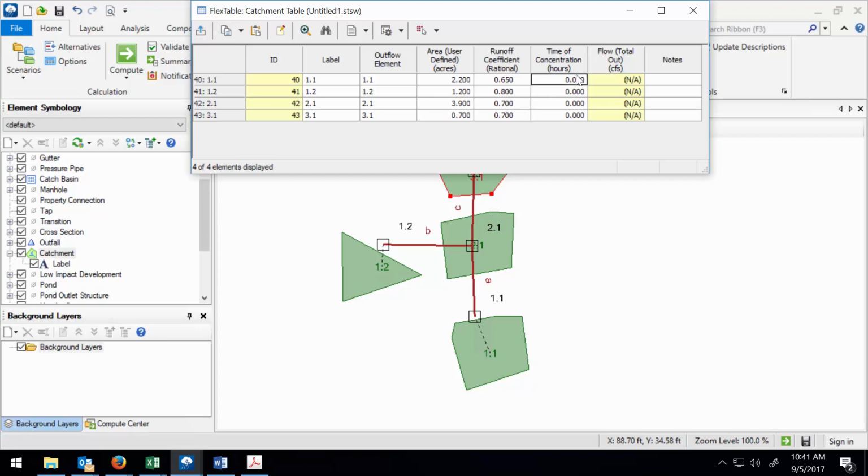All right. Time of concentration, that's what you could estimate by going to a place and watching the water travel from all points in the watershed, or you could use one of the estimating schemes, like Kirpich or all the other methods. So right now it's in hours.